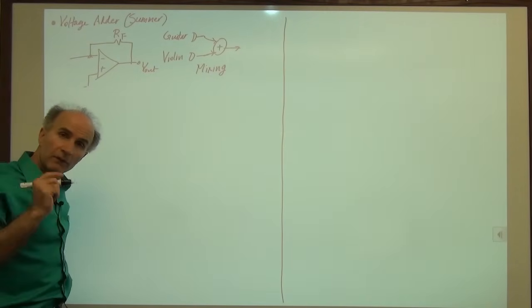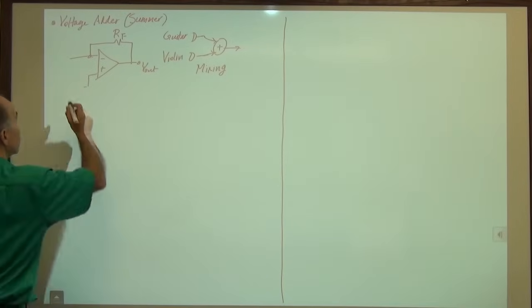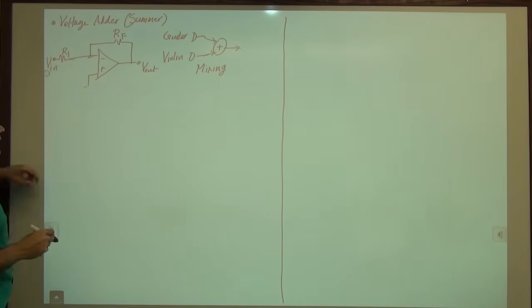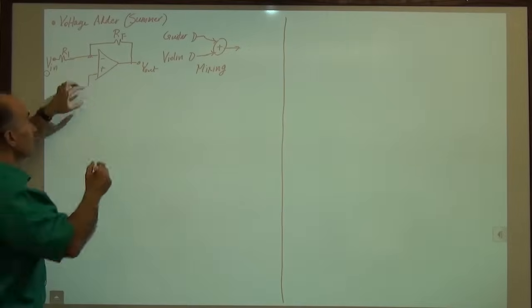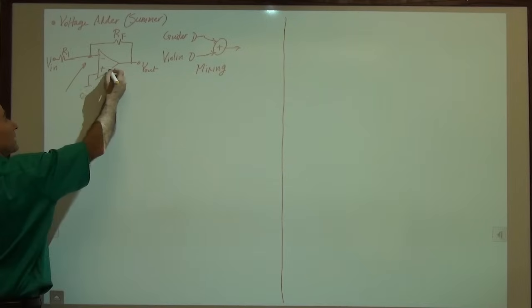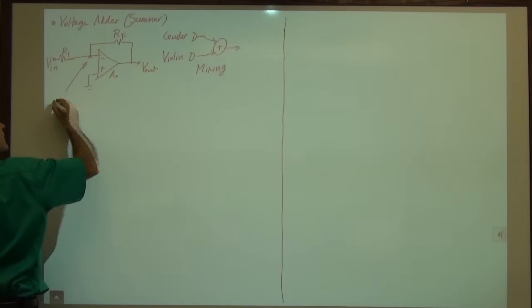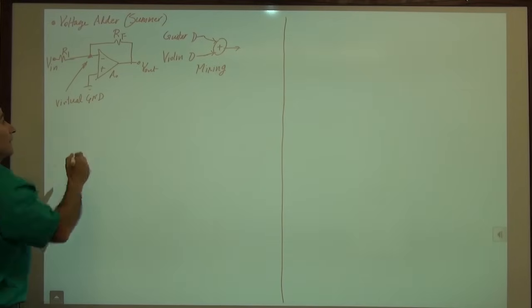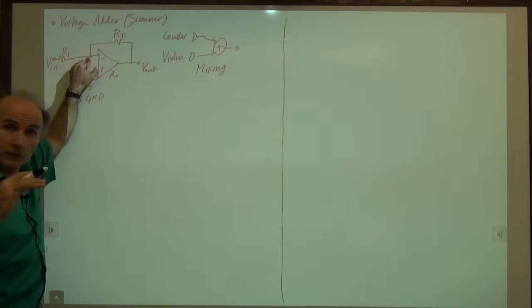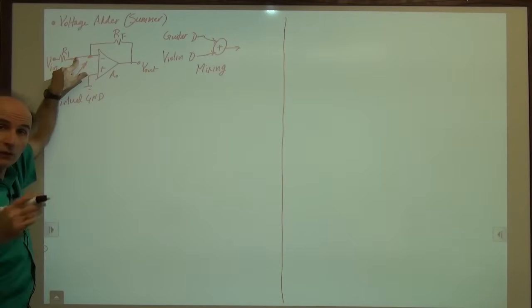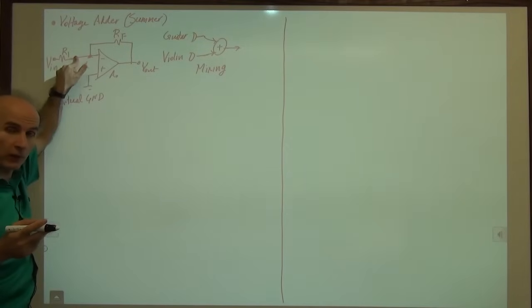Now what I remember from the inverting amplifier topology is that if I have a resistor here and I apply a voltage here, then by the effect of this virtual ground, if A0 is large, this voltage is close to 0 and doesn't change much, which means the current through R1, to a good approximation, is just Vin over R1.